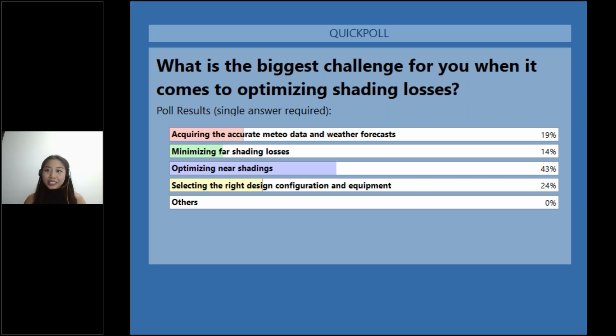TMY data, which is the meteorological data. It is a cornerstone for solar plants because the irradiation is basically proportional to the energy yield you have in the end. PV Design provides you free databases, or you can also choose to import your own weather measurements, and we will synthesize them and generate an hourly resolution of the horizontal irradiation, DHI, or the diffused horizontal irradiation, and ambient temperature, etc., based on our model on a TMY year.